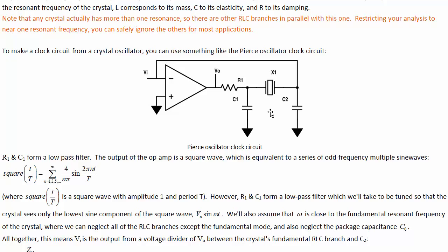You don't want that to affect what the output of the frequency is. You don't want the computer to start trying to run faster or something because it's hotter. And certain cuts of quartz have essentially no temperature coefficient to their resonant frequency, so we can make really accurate timing circuits that work over a wide range of temperature.